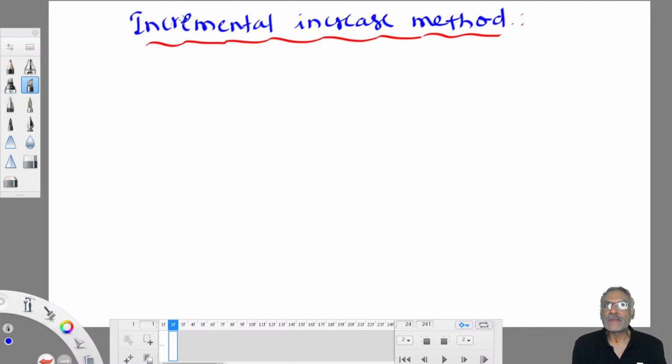So exodus happened. Because of that exodus, if you compare the growth rate, I am talking about growth rate, population always increases, population never ever decreases. But if you see Srinagar's growth rate during the 60s, 70s, 80s, it was positive. But during the late 80s and early 90s, even late 90s till 2010, the growth rate drastically decreased. If such a trend is there, then we have to apply the incremental increase method. Confused trend: sometimes growth rate is positive, sometimes negative.